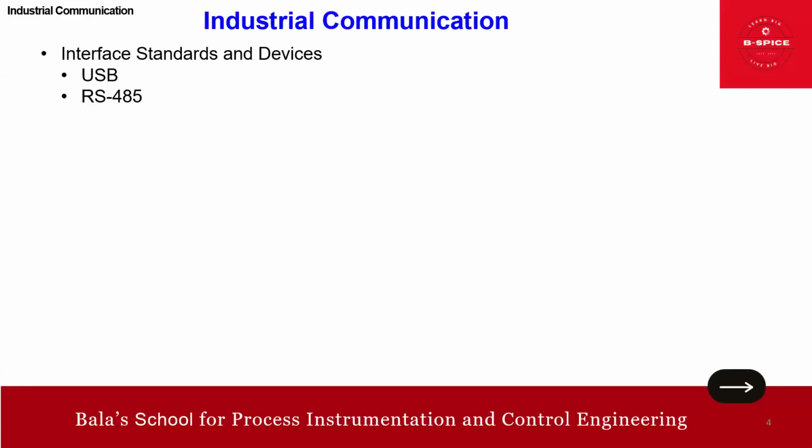Most often the RS-485 network consists of point-to-point connections to nodes from a bus cable. Twisted pair wiring is used for the bus cable. RS-485 offers high immunity to electrical noise when implemented properly. Of course, we need to have a terminator at the end of the network to minimize such issues. In an RS-485 network, one master device communicates with the slaves.